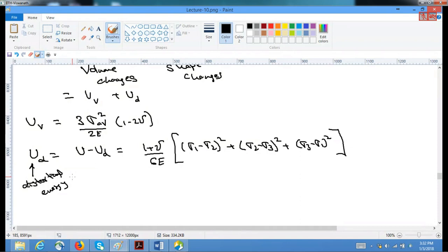So like that, what we are saying is there can be two different stress states. Each component can be different. Sigma xx can be different, sigma yy can be different, xy can be different, yz can be different. But if these two states, whatever they may be, have the same distortional energy, then they are equivalent. That is, they will have the same yield locus, or they will yield at the same place. That is what has been done. So since we have done this for a uniaxial stress state, when we are doing a stress strain curve, in a uniaxial state,